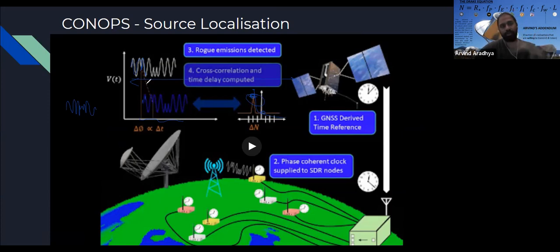So in terms of real time, coming back to your question, if I'm recording for 1 second, then by definition I need to search across 1 second. If I'm sampling at 1 million samples per second, then I have 1 million samples here. Then I need to do that computation with 1 million samples multiplied by 1 million samples and check the sum, and then slide them by 1 sample, slide them by 2, and so on, and sweep them completely with respect to each other. And it is computationally intensive to do that.